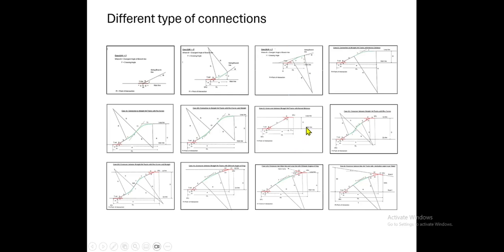And of course, crossover. Between two parallel lines we want to introduce a crossover. That means we are introducing points and crossing in both lines. Connection means here the movement will be only through the points and crossing, the turnout movement. But in the loop line it is only one movement. Here in the case of a crossover, both the points and crossing permit straight movement as well as turnout movement. Okay, it's called a crossover.